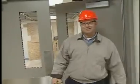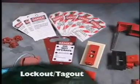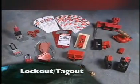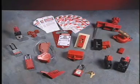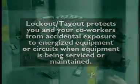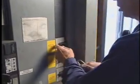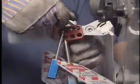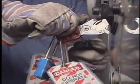Before we wrap things up, let's take a look at a few more important safety issues you need to keep in mind. Lockout-tagout is the process of using locks and tags to block the flow of energy from a power source so equipment won't accidentally release energy or start up. This protects you and your coworkers from accidental exposure to energized equipment or circuits when equipment is being serviced or maintained. Lockout-tagout affects everyone who comes in contact with energy-powered machinery and equipment, although only certain workers are qualified to apply lockout devices and tags.